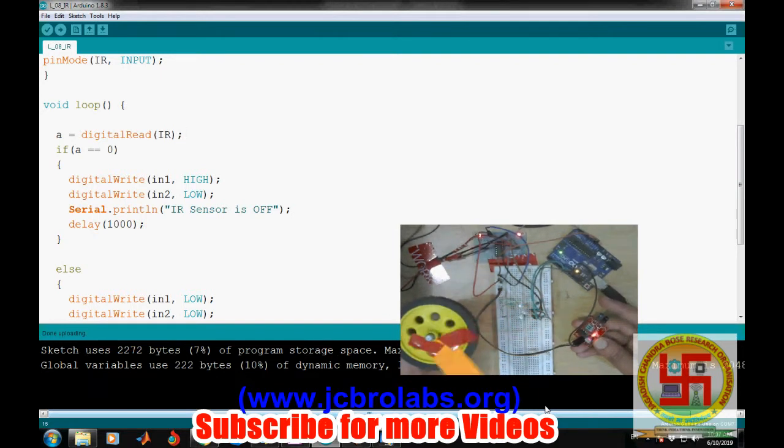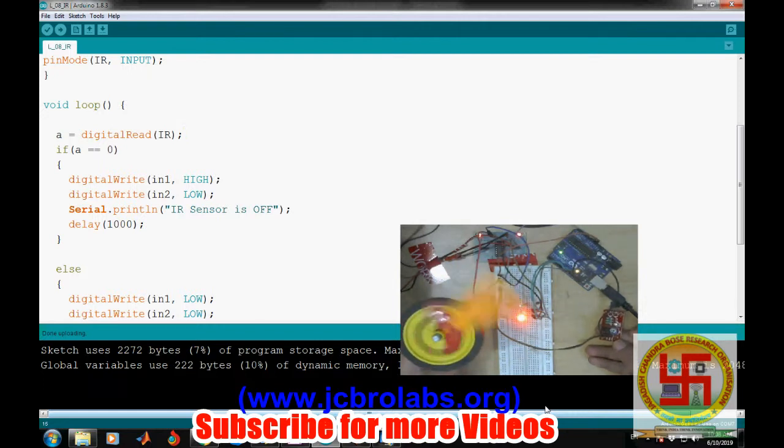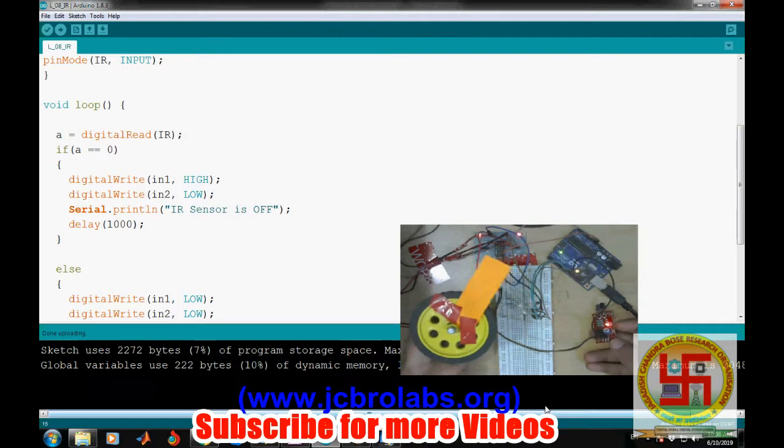Yeah, one more thing which is very interesting with respect to this IR sensor, if there is a black surface in front of it, it will not detect it. Like this wire is black in nature, right? So it is not detecting it, it is showing there is nothing in front of it. Because black absorbs all the light, it is not showing anything. But as soon as I put it towards the table, it will start indicating, okay, there is an obstacle in front of it. So this is one of the very crude drawbacks. This IR sensor is a very crude sensor for obstacle detection. So it is detecting the table but not this black wire.